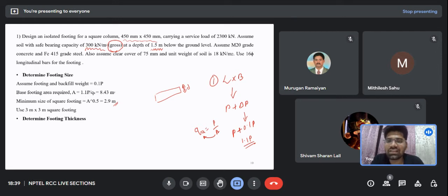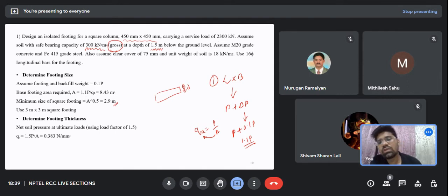What are the design criteria for depth? One way shear and two way shear. So let's first check it for one way shear. Now again please remember, I already told you that to evaluate the size of footing I'm using the working stress method.